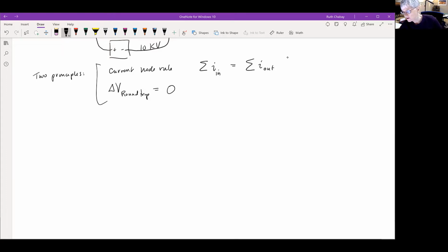We also need some definitions. Remember some equations we worked out, where the number of electrons per second was equal to NAv, where N was the density of mobile electrons, A is the cross-sectional area, and v average is the drift speed. And v was equal to the mobility times the net electric field. So the electron current we could write as NAuE. And conventional current was just q times i here. And this is electrons per second, and this is in coulombs per second, or amps.